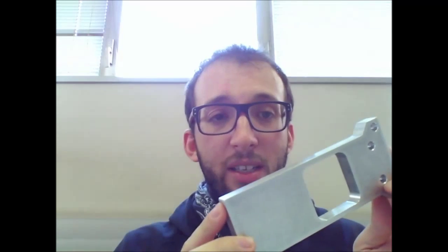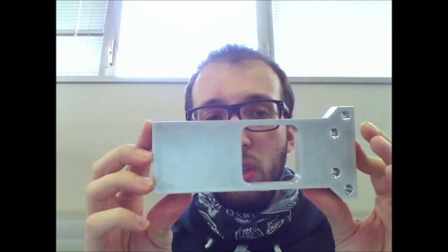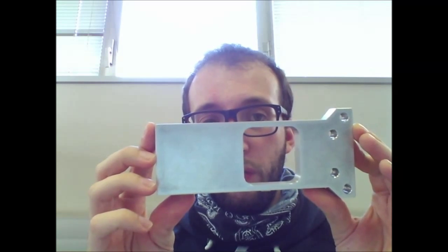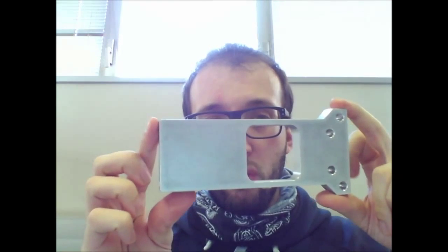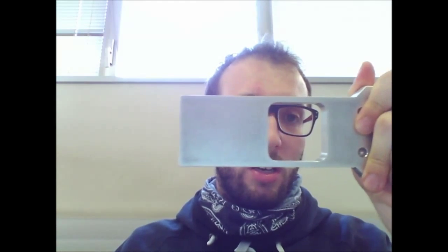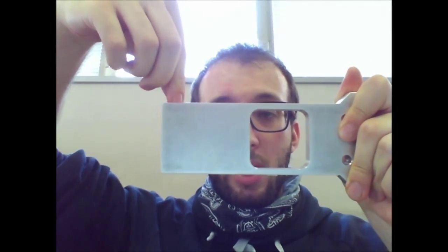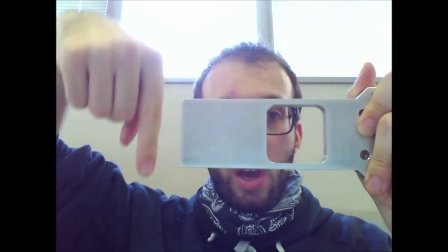This is a load cell I designed for a control purpose, for specific tasks. Those cells, as you see, are mechanical systems which are subjected to specific kinds of forces. For instance, this is a flexural load cell. This works with bending. In fact, in this region the load cell is clamped and forces are applied in this way.